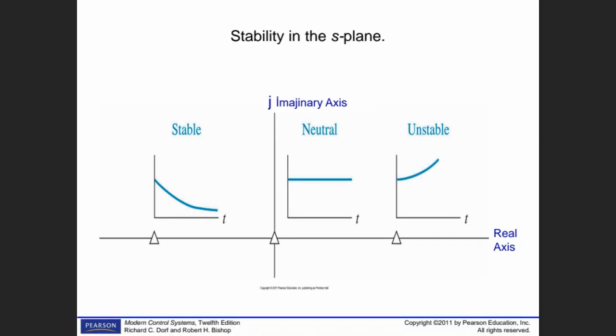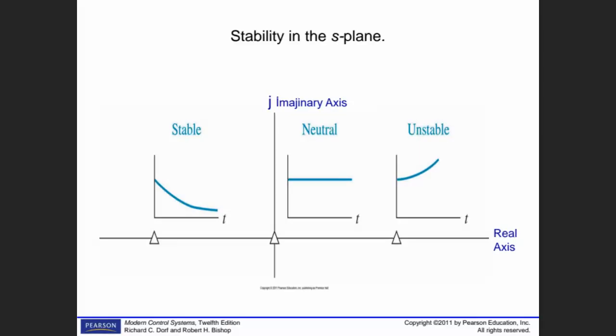If one root is in the left-hand side, you can follow my cursor, please, without any oscillation since the roots are located on the real axis, and another root is at the origin, then it's a continuous signal, and that one is unstable.